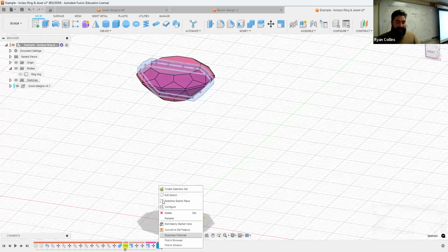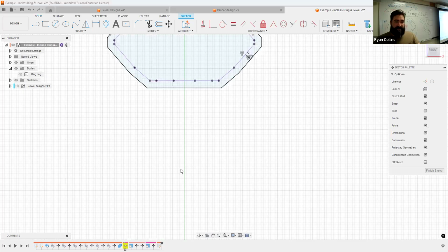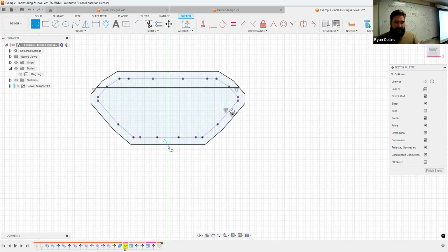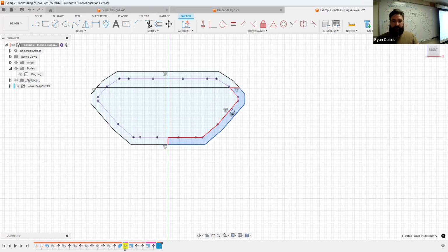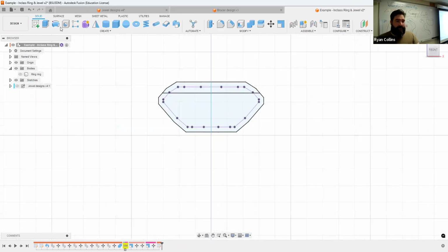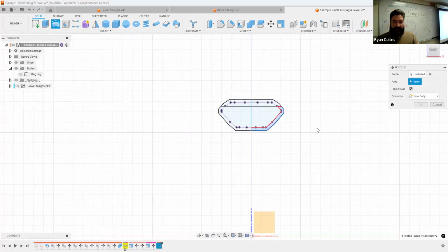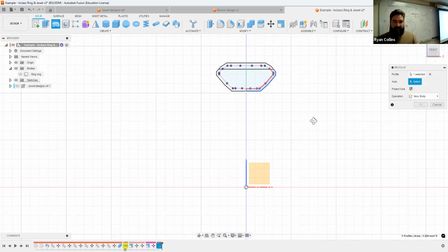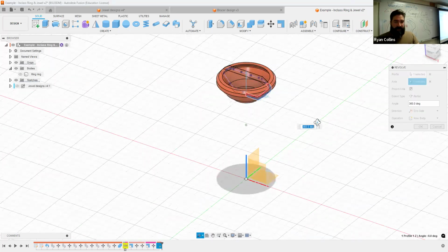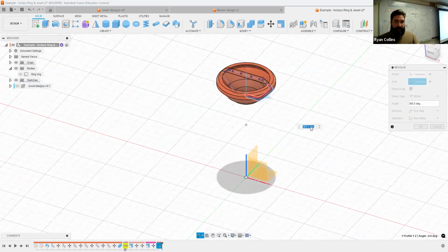Fine. So I just need to chop that up a little bit more. So all that means is put another line, smack in the middle, divide it. Cool. There we go. So see, now I can just isolate just that circle or just that partial. Cool. All right. Now use the revolve tool. That partial piece revolved around the z-axis. Now this makes for a weird circle here.